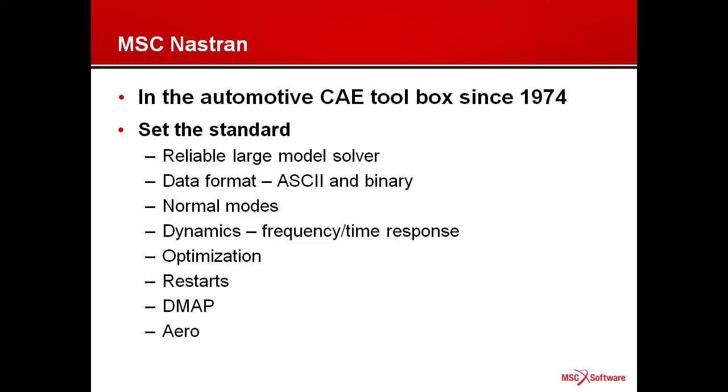Restarts have fallen out of favor because the computers have gotten very reliable. But when it comes to these very large models and restarting into the modal solution space for the dynamics, when you're doing 60,000 restarts a year, it makes a big difference when you don't have to calculate those modes 60,000 times. And DMAP lets you get into the code. Many people use it to insert their own solvers or their own techniques, and actually commercially sell that DMAP to end users and companies.